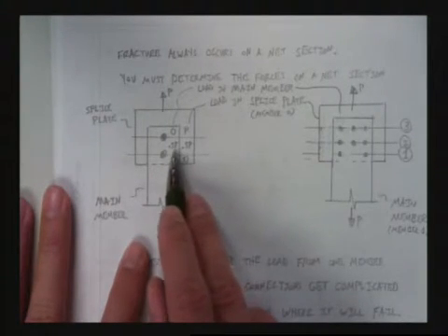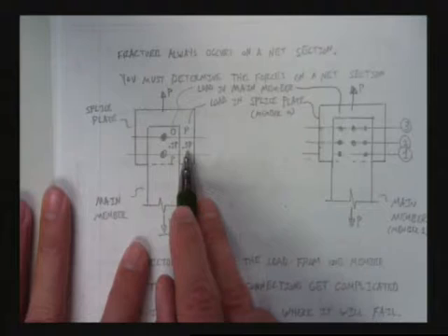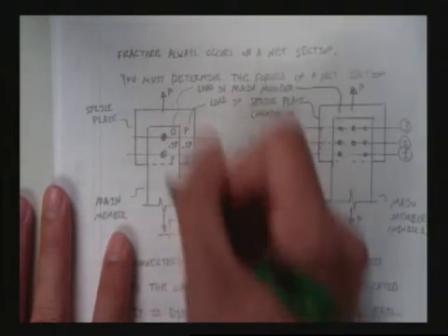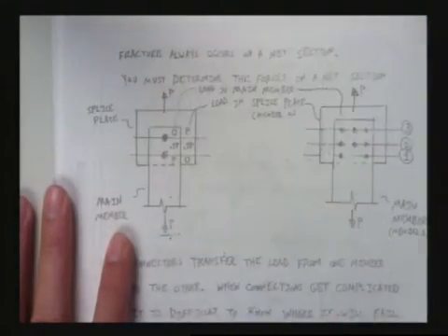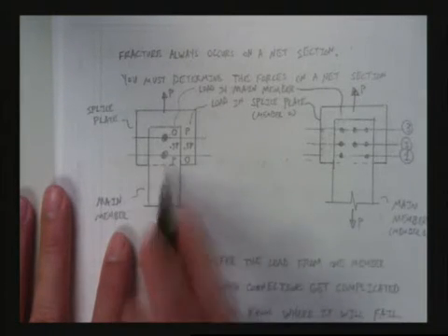And I say the load in the plate now is only half P. And the load in the plate underneath is half P. What? How can that be? Well, if this load is P, how is the load going to be transferred from this plate to this plate? Through the bolts, right? So if this load is P, what are the bolts going to take?